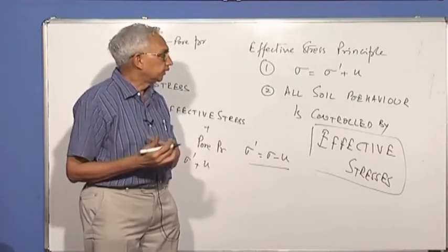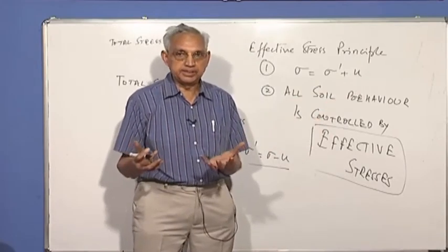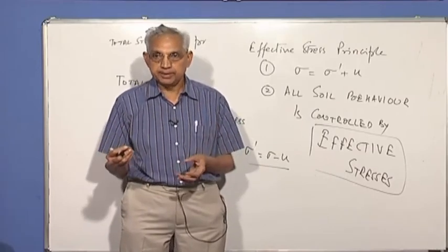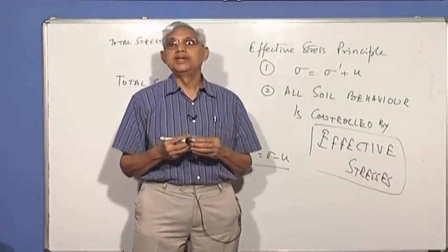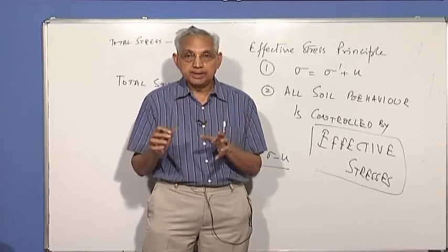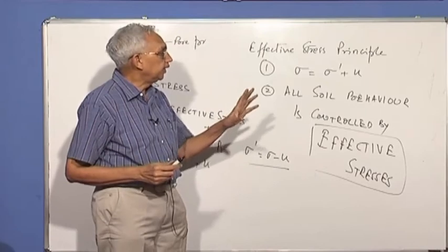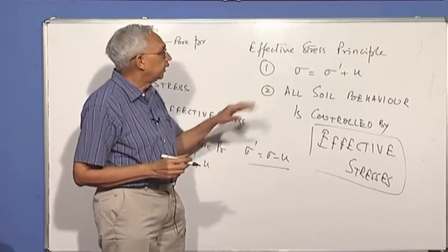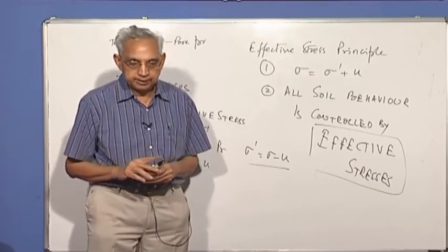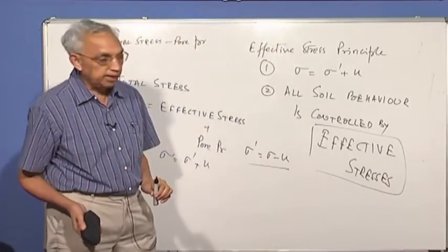You may increase the total stress. If the pore pressure is increased, the effective stress will not change. If effective stress does not change, the soil does not change in its behavior. It will not increase in its strength, it will not show any deformation, and so our analysis will not be correct because we are not able to identify what is happening. So what Terzaghi gave in 1925 and later is the effective stress principle, which is the basic thing for all soils, and we now like to look at that as the starting point for all our analysis.